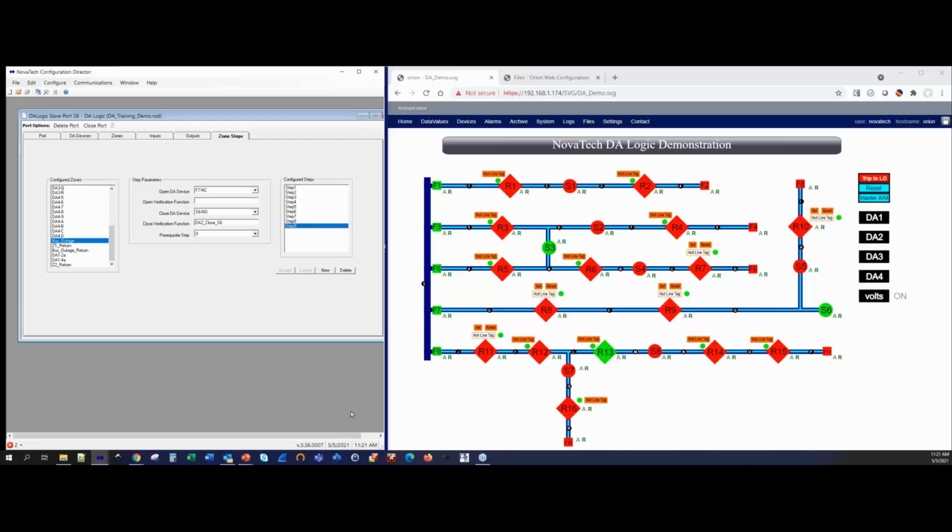So I do not recommend some kind of an automatic restoration of normal. The exception would be if you wanted to have an automatic switching schedule to put the system back to normal after you know that the crews are clear. So that would be a case, for example, after this bus outage.